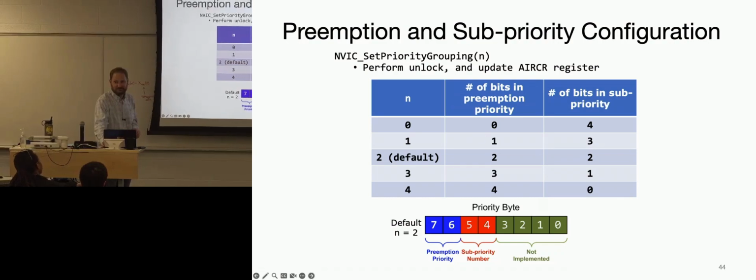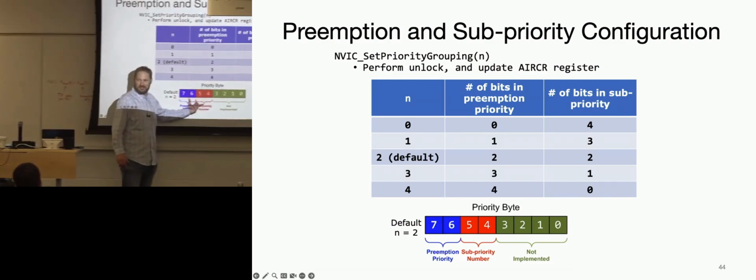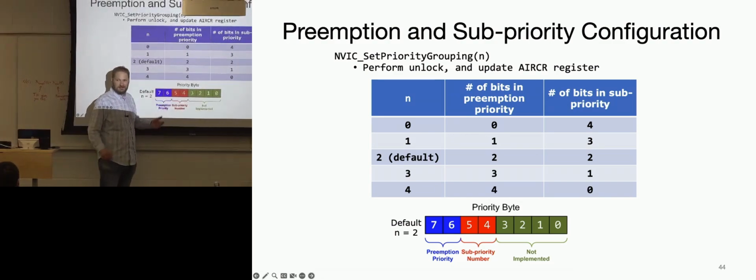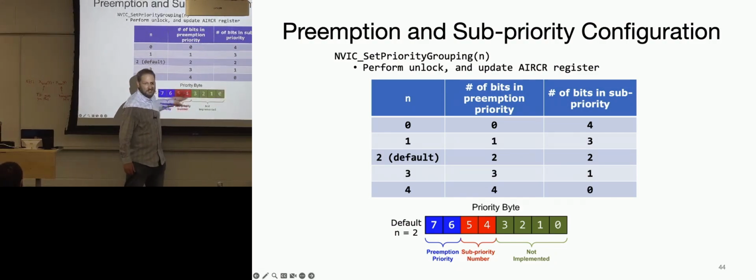They're not using the 4 least significant bits. When I just make a 4-bit priority versus an 8-bit, why would you choose this? ARM says you have to have 8 bits, okay?